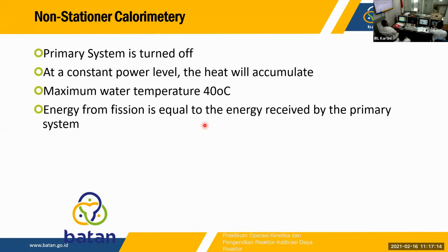the demineralization system, because the resin and the filters of the demineralization system are a lot more sensitive to the changes in the heat. Therefore, if the temperature of the water gets too high, they may damage the filters and the resin inside of the demineralization system. Besides that, having a high water temperature may increase a little bit of the fatigue of the materials inside of the reactor tank, and it may increase the rate of aging in the reactor tank.